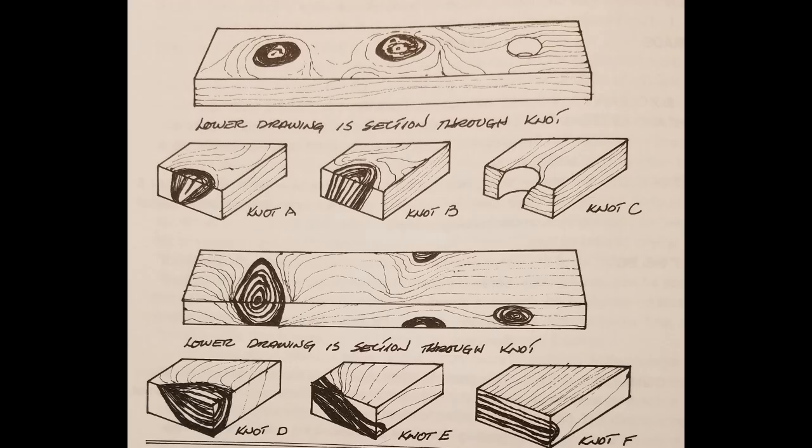Here you can see the most commonly seen defects when it comes to dimensional lumber. Depending on the grade, you'll either see the knot go partially from one side, tapering down. You'll see them either go all the way through, or depending on the drying process or expansion due to moisture and humidity, the knot may have fallen out altogether. Versus some of these other ones where, depending on how the piece was cut, you may have the knot stretch from one side to almost the entirety of the board width. Or most commonly, you'll see that the knot goes all the way through, such as that middle section there. Or you'll just have it barely visible from one side or the other.